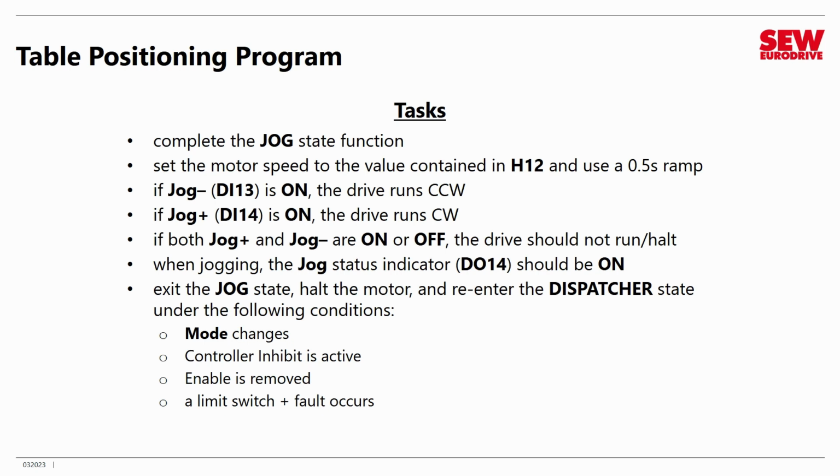We're just going to add to that. You'll need to do the following things. You should set the motor speed to the jog value. Remember, that's contained in variable h12, and I'd like you to use just a hard-coded 0.5 second ramp, 500 milliseconds.